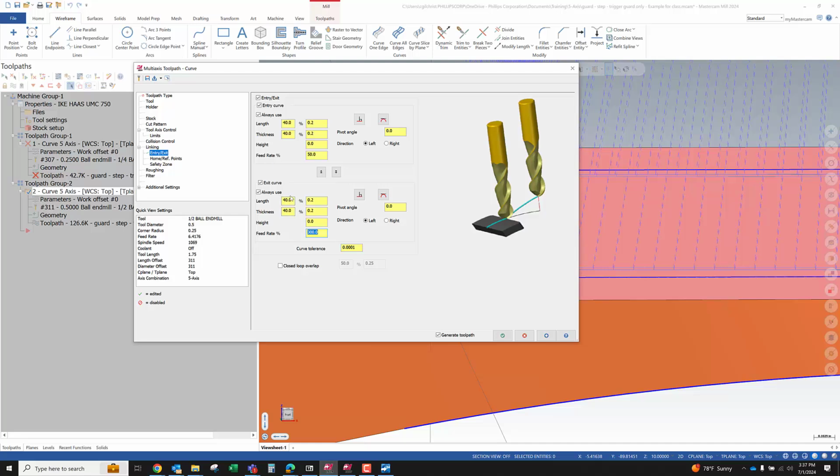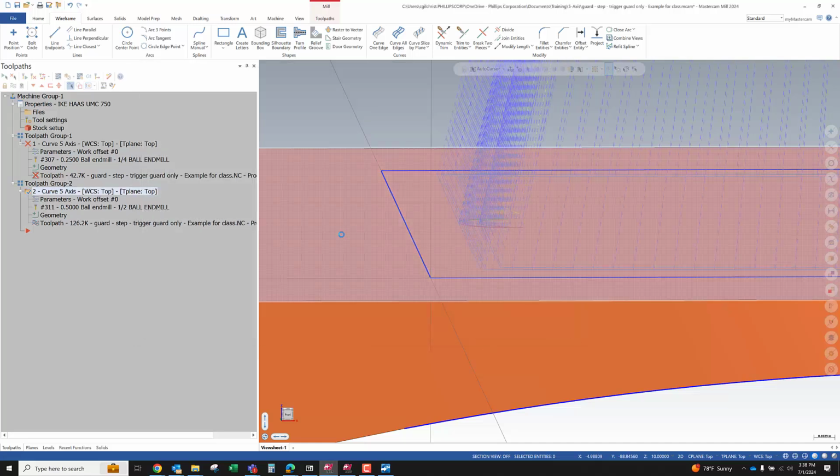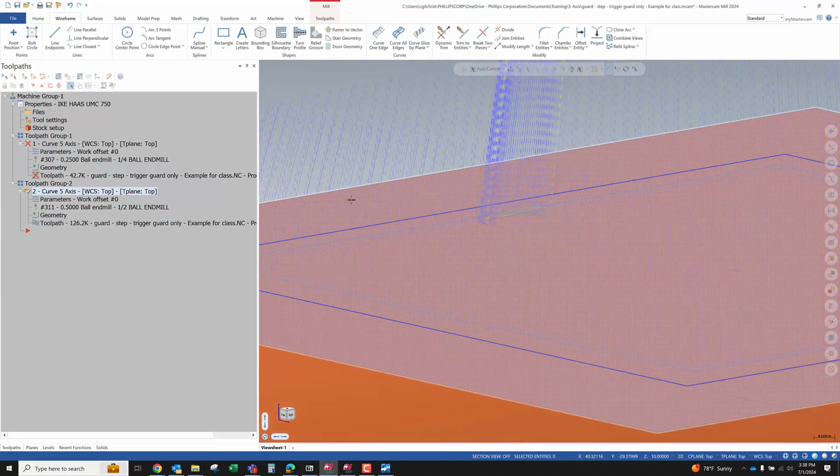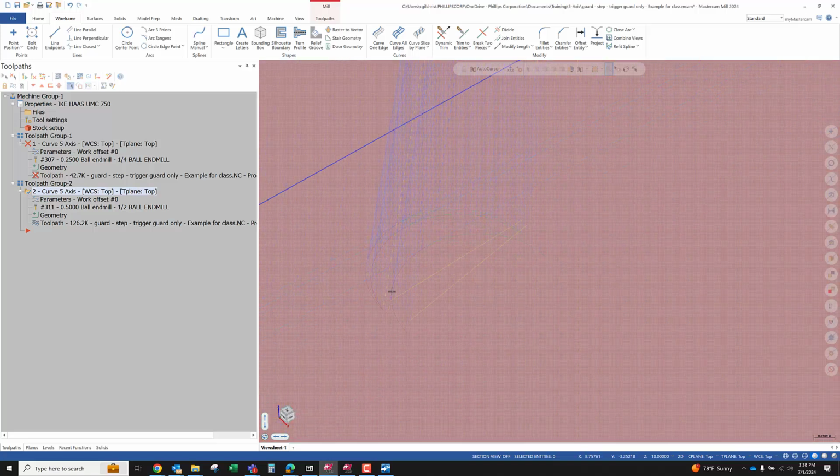So, hey, we're all done cutting. The cutting force should be lessening as we come to that final piece of overlap. Now let's speed up on that exit curve so that we're actually making some time. And the other thing that we could potentially do under here, because we're using clearance only at the start and the end, let's do 100 thou for the retract and 100 thou for the feed plane. And provided that this motion doesn't cause us to bump anything, which it shouldn't, because it's executed with plenty of lead in.